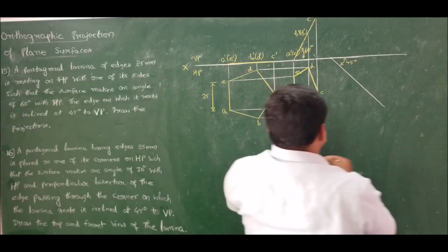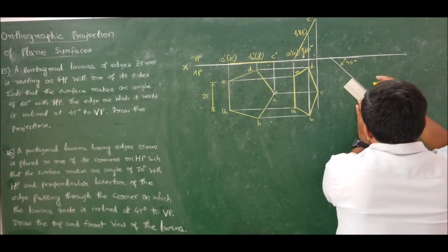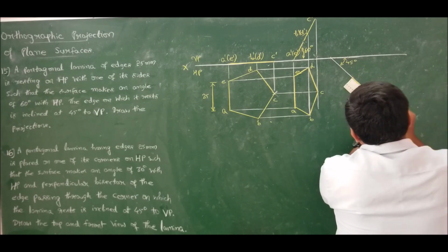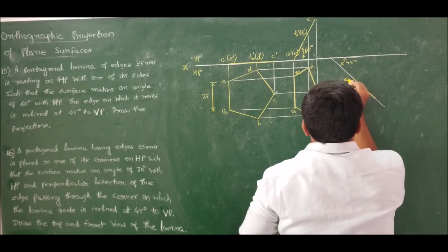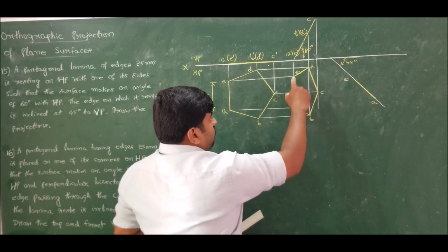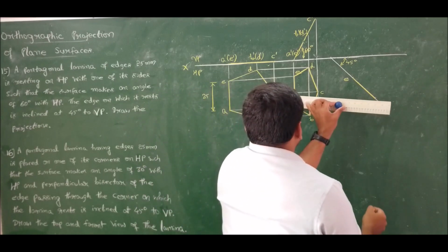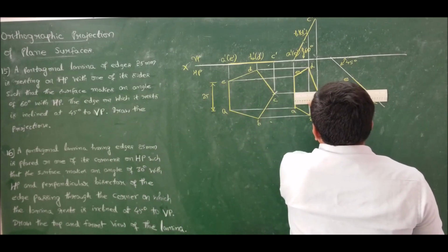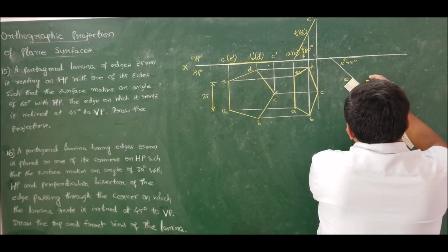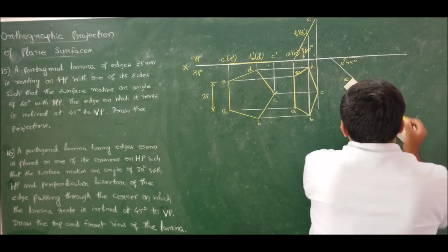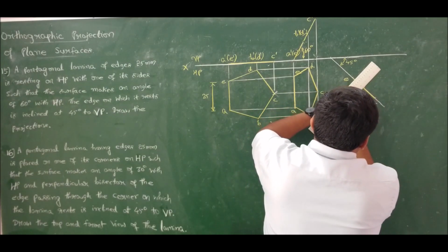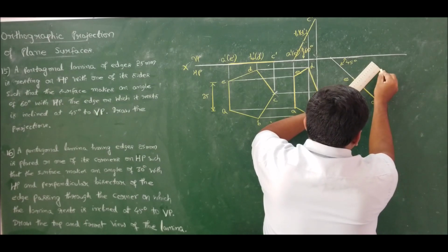Now we know how much this is. This is 25 mm, so mark 25 mm on this line. I have drawn 25 and call it E and A. Now we know that C is on the perpendicular bisector of AE. Since it is a perpendicular bisector, divide this 25 mm into 12.5 on either side and transfer the point C, which is perpendicular to this.